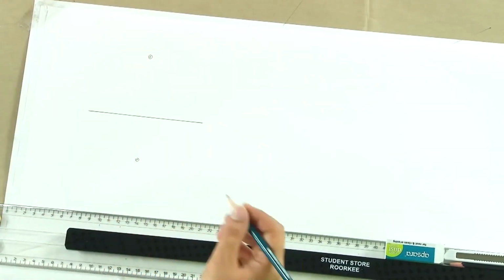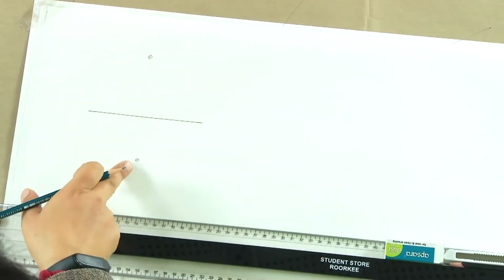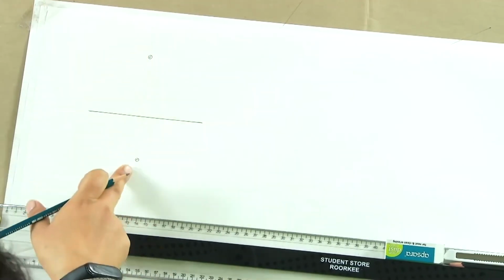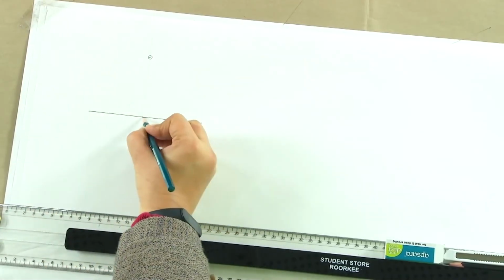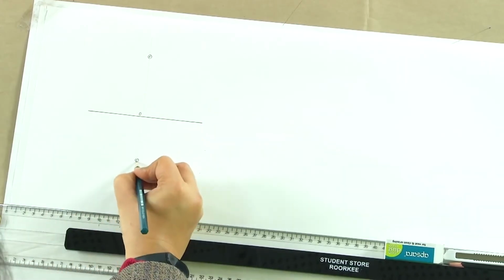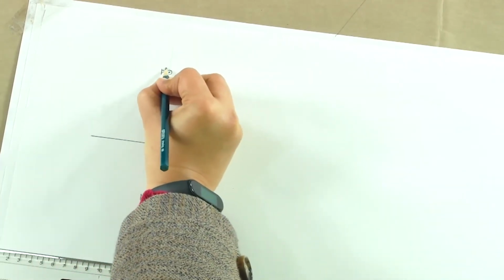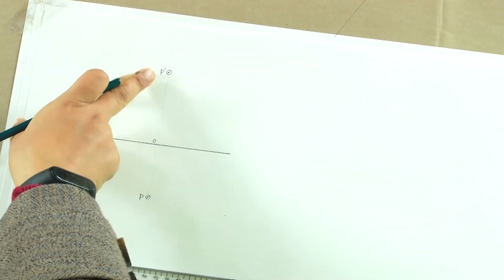The nomenclature is the projection, and this line, this thin line which is passing through the top view and the front view, is the projection line. Where the projection line is meeting the reference line, in this case, we will just mark it as say O. And this one, say the point was P. So, the top view will be marked as small alphabet p and the elevation will be marked as small alphabet p dash. That is the nomenclature.